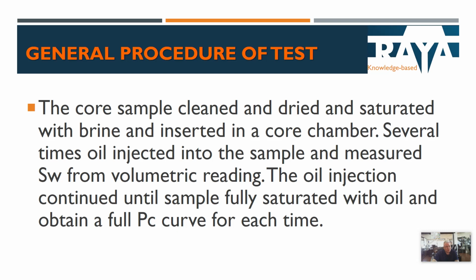In every injection, we increase the pressure, and the injection of oil continues until the sample is fully saturated with oil, and we obtain a full PC curve for each rock type. This takes different times, which change by the test method.